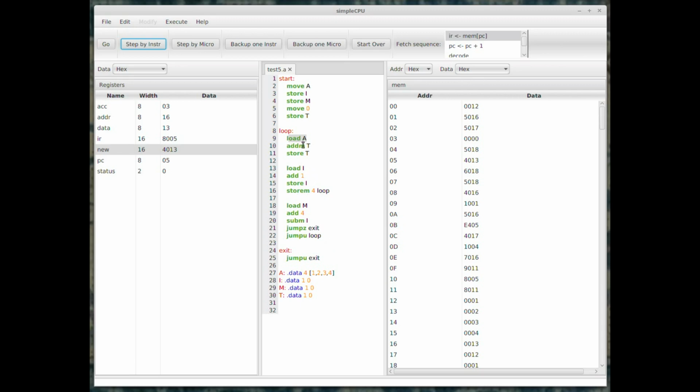And now, obviously, I have modified this load instruction. Previously, remember, it was a load from address 12. It was pointing to the first element of that array in variable A. But I've modified it now, so it points to the second element of that array. So now I can implement that for loop. I have a mechanism that allows me to adjust at runtime the address that I will read with my load instruction. And just to emphasize, we will be doing this the proper way in the Simple CPU version 1D. We will be using register indirect addressing modes, which we'll come to later.